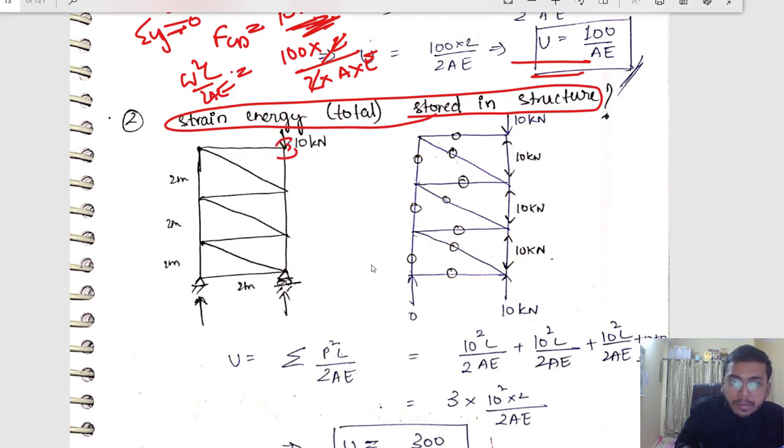If you see this joint properly, if I apply sigma x equals 0, I know this member is a zero force member. Agreed? Once I know it is a zero force member, I can ignore it. Now it is similar to 2 members meeting with no external load. So this is 0, this is 0. Simple.